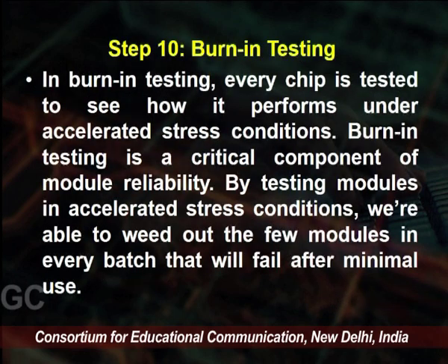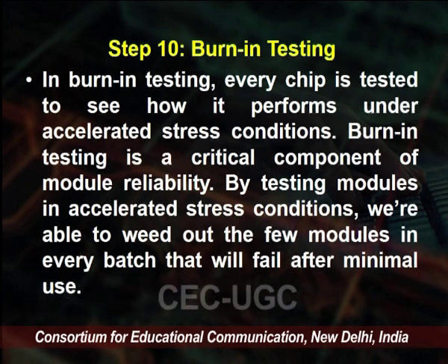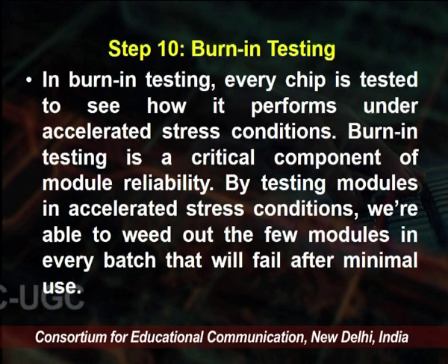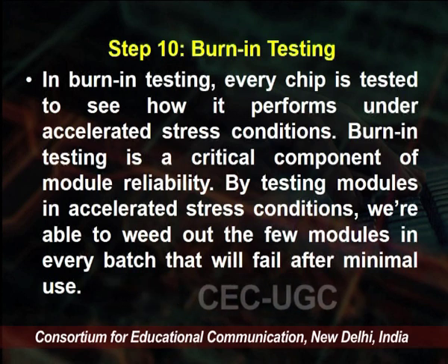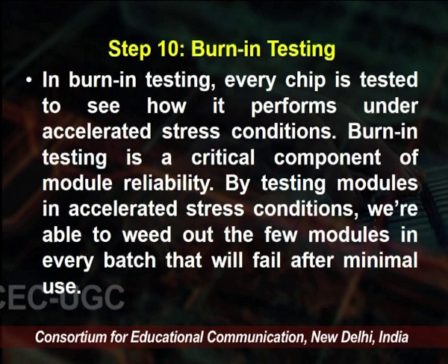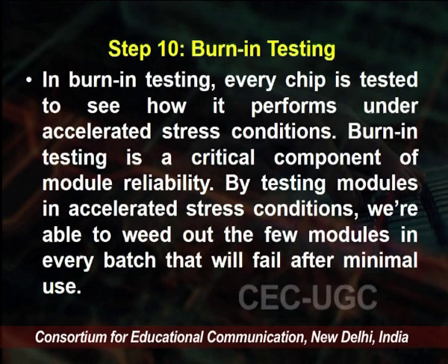The next step is burn-in testing. In burn-in testing, every chip is tested to see how it performs under accelerated stress conditions. Burn-in testing is a critical component of module reliability. By testing modules in accelerated stress conditions, we are able to weed out the few modules in every batch that will fail after minimal use.